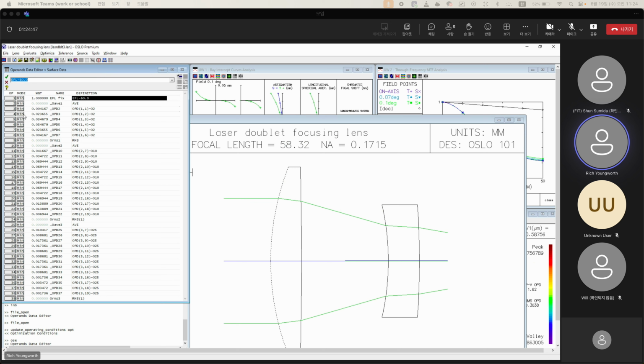Right now, all of these are set to be minimum. This mode, if I switch it to constraint, what it does is now it will use Lagrange multipliers to nail and make absolutely certain that one is satisfied, and then it will do the rest. So you have to make sure you have the degree of freedom available to do all your constraints. So if I have 5 constraint mode ones, I better have at least 5 variables. Otherwise, it minimizes the function to a set of constraints.